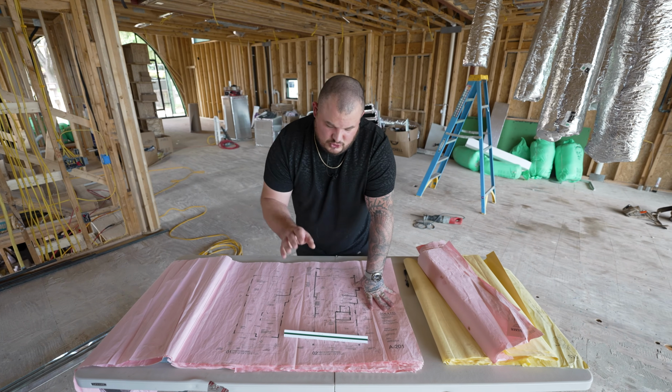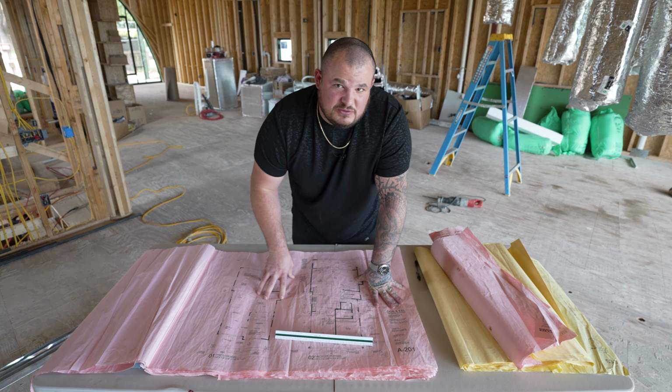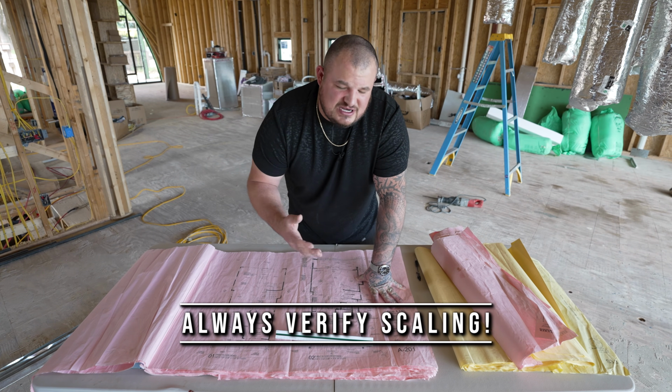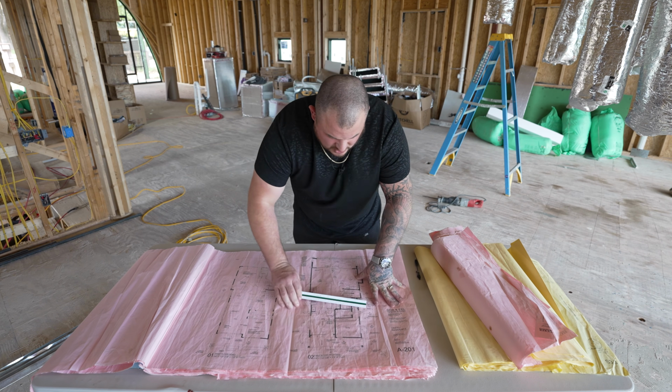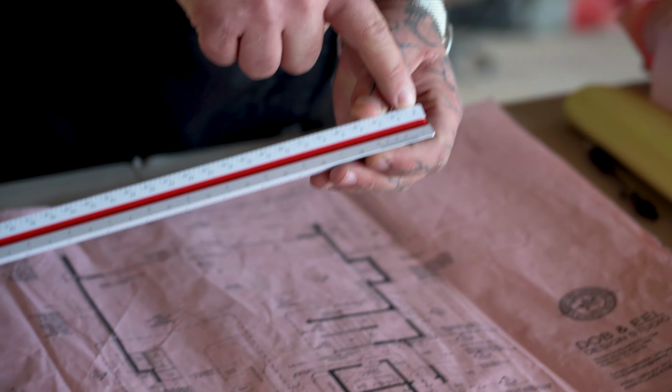Let me tell you, do not believe this. When you print these plans, they have to print them to scale. There's a lot of verification that you have to do. So what I do is, this is 1/4 is 1 foot. So on the scale here, I find 1/4.